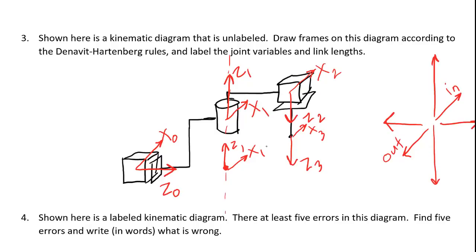Now you might think it's strange that the 1 frame is now not attached to any part of my robot, but in fact that actually doesn't matter. One way to understand this is that we can imagine that there's a link, let's say, connecting between here and there, and that this axis is attached to the end of this link, and we would achieve the same thing.